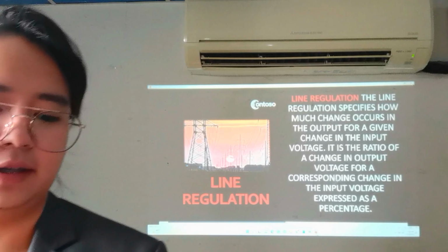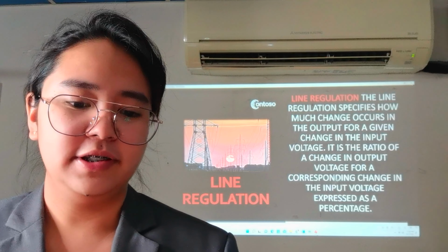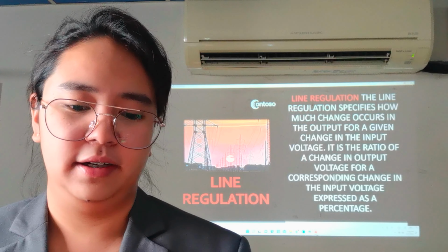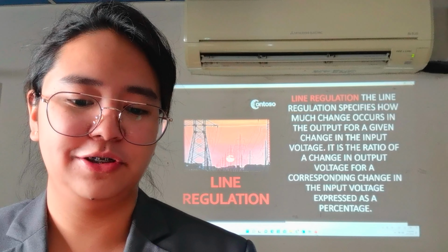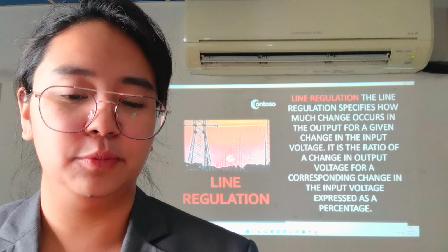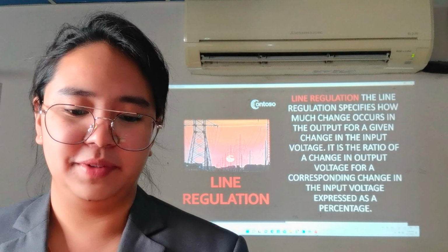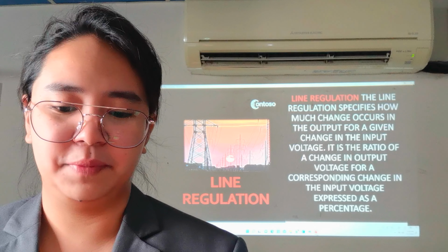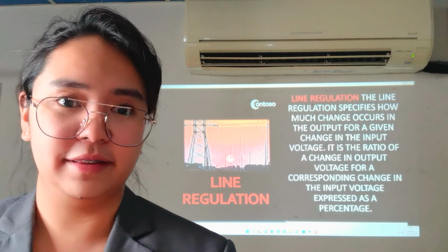Okay, next is regulations. Line regulation. The line regulation specifies how much change occurs in the output for a given change in the input voltage. It is the ratio of a change in output voltage for a corresponding change in input voltage expressed as a percentage.